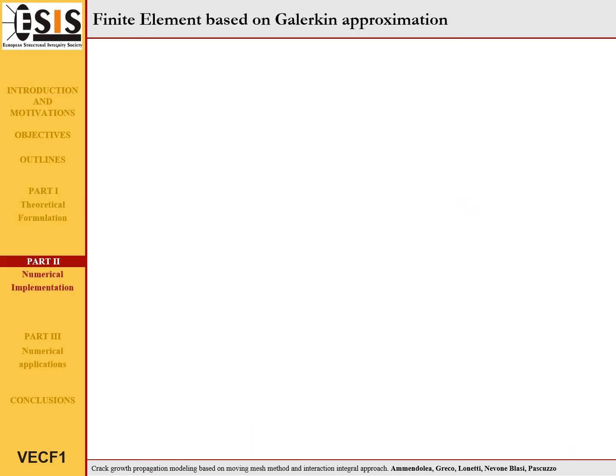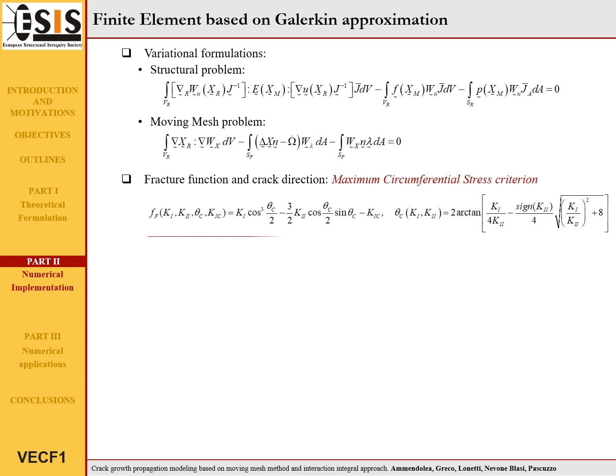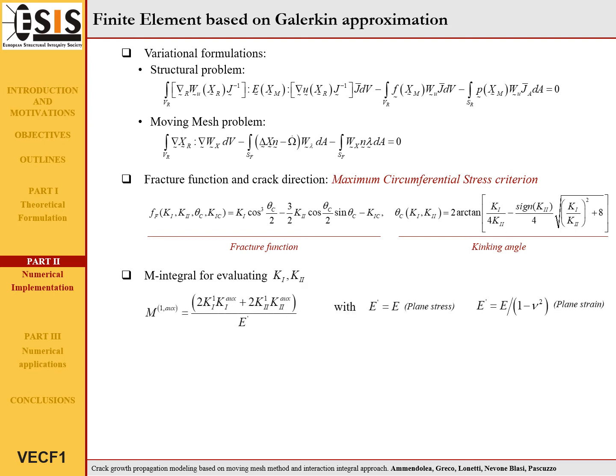The governing equations are implemented within a finite element framework based on a Galerkin approximation. In this framework, the governing equations are expressed in a variational form. One relevant aspect consists in the definition of the fracture criterion and the direction of crack propagation. To this end, the maximum circumferential stress criterion has been used in the model. The stress intensity factors are evaluated by means of the M-integral, considering as auxiliary state the solution of pure mode 1 and pure mode 2 of a straight crack in an infinitely large sheet.